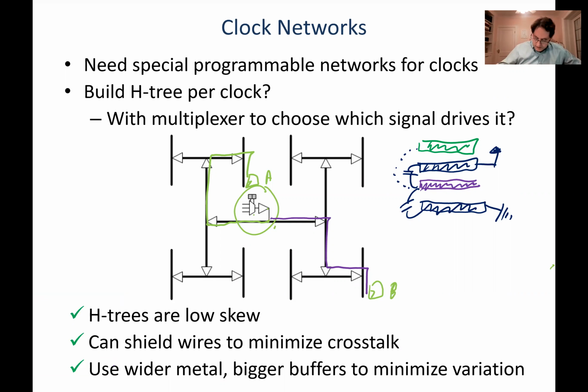And now let me get all my colors here. So let's look at this purple wire. That's my clock. I'm now drawing it from the end view, okay? And I've got my shielding wires beside it. So here's one shielding wire. Here's the other shielding wire.